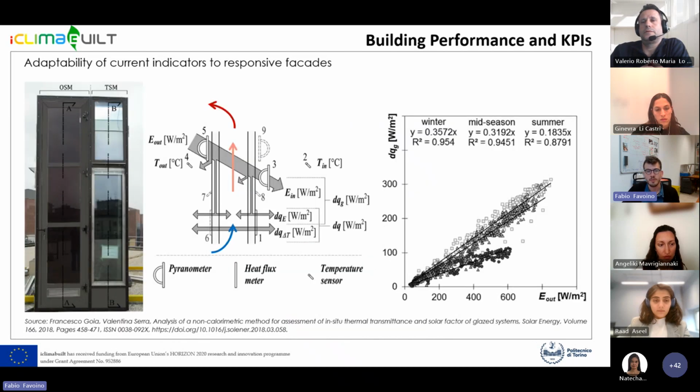In the same way, if we use ventilation within a cavity, you can see that the g value, which in this graph is the slope of this line, inherently depends on the solar geometry, but when you use ventilation as well, there's a large change between the g value in summer or in winter conditions.